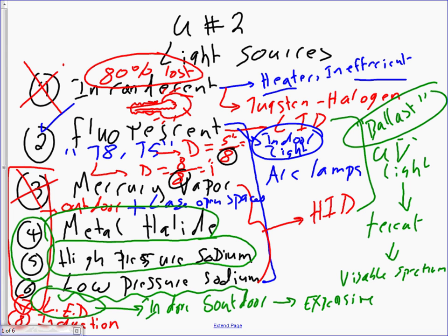They treat the light. So be aware, if you're doing a parking lot, did you guys remember the MH fixture, that CAD fixture that we used? Do you guys remember that? That was coming from metal halide. We used metal halide. Typically, metal halides are commonly used in parking lots. High pressure sodium, you can also use them in parking lots, but also streets and highways and so forth.